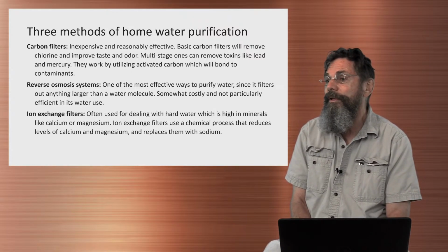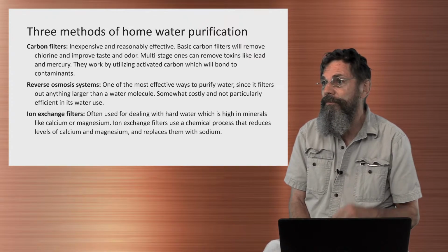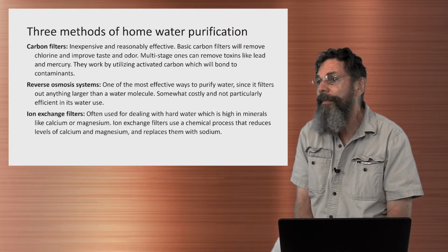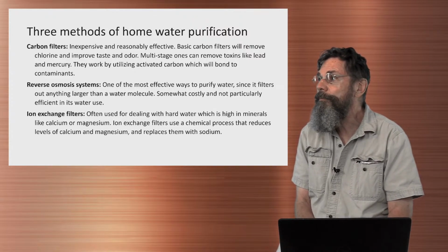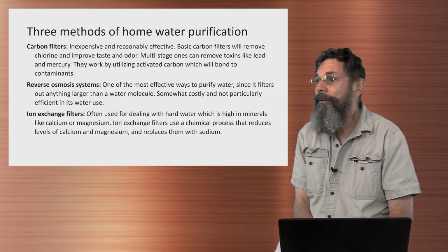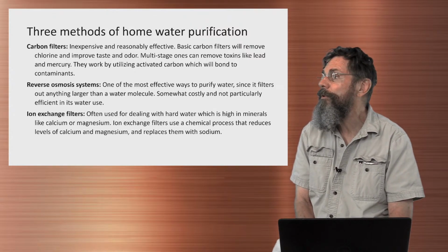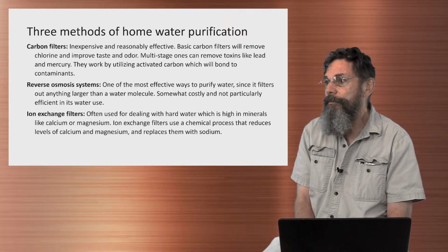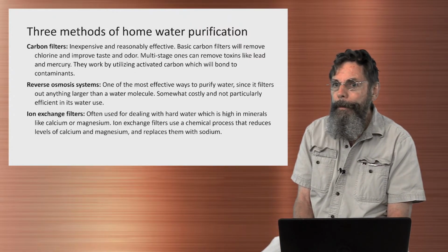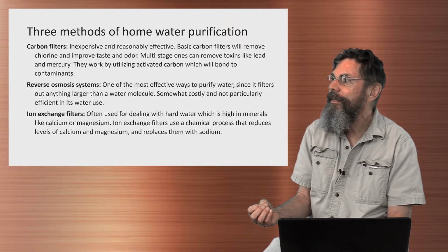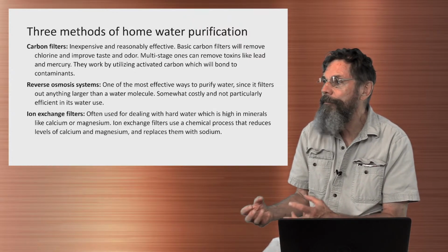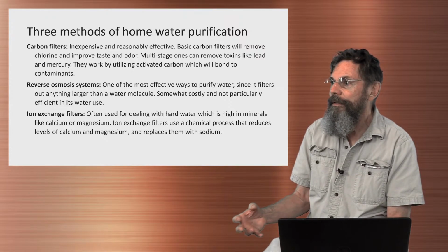In extreme circumstances, people who are on a very low salt diet or just really can't tolerate a lot of salt in their food or water, it would not be suitable. There are other processes beyond that to strip the salt out as well, but you should be aware that the ion exchange filtration or hard water filtration does deliver water with a sodium content. And again, they have to be purchased and they have to be maintained. There's a zeolite or other type of content in there that attracts the magnesium and the calcium and builds up over time. That builds up and that has to be flushed out and the process continued.